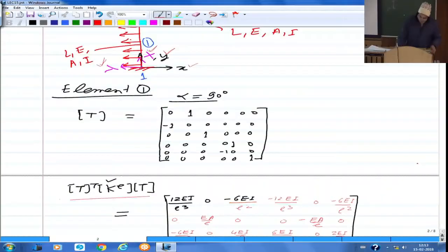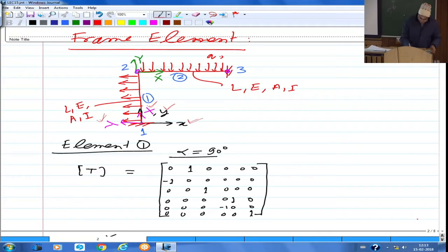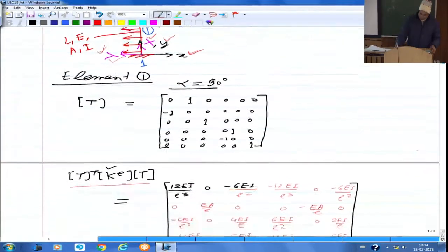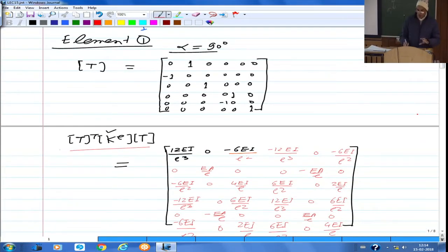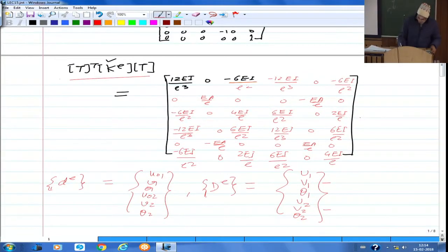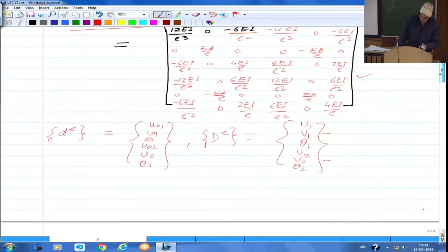and the changes in sign because of this particular change in direction, this being in the opposite direction of the local y axis. So wherever it is displacement and force, the minus becomes plus, but displacement and rotation would be plus minus, equal to minus. Similarly, moment and displacement would be plus minus, equal to minus. Moment and rotation would become minus plus. So you can work out these relations yourself. I want you to look at which of the signs have changed and which have not changed, and why they have not changed and why they have changed. You can look at that based on the coordinate directions I just mentioned.